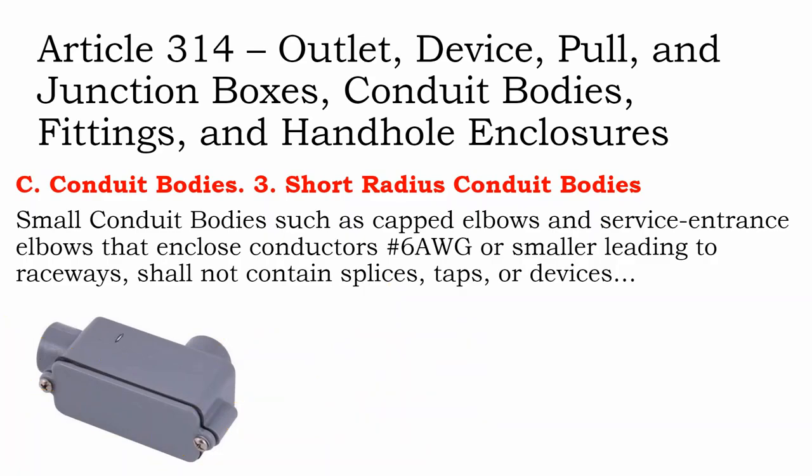The other reason you use LBs is when the customer says, I like the way these LBs look better than a 90-degree bend. You could have a 90-degree bend, but it would start bending over here and take up a lot more required space with an EMT tube, whereas with an LB, you get a nice sharp edge.